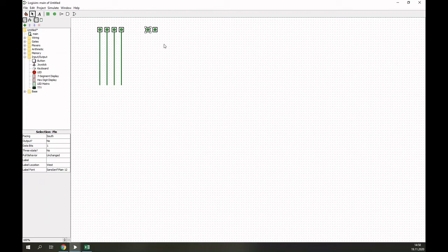So what we have here, we have a truth table, and therefore we can just do the following. We put an AND here so that we get the first line. We have 3 inputs. And we do 0, 0. So this means we do 2 negations here, because this is the first of our truth table.